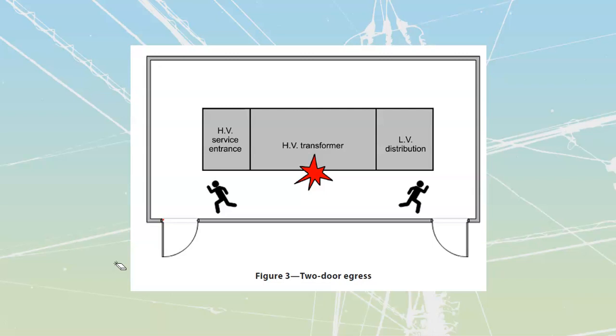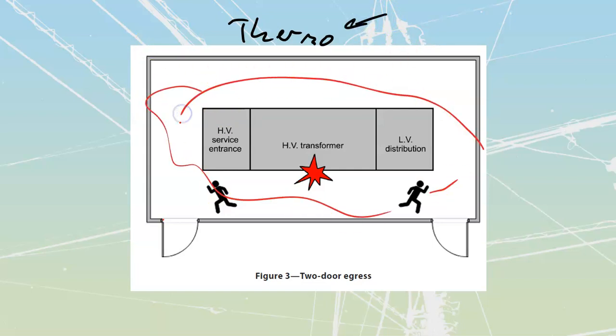Remember, breakers are a thermomagnetic device, which means that thermo, that's that Latin root over there, means to do with heat. They're going to be sensitive to heat. So if this whole room inside of here gets really nice and warm, we're going to start to have breakers, because they're keyed by heat, that are going to start to trip inside of our service.